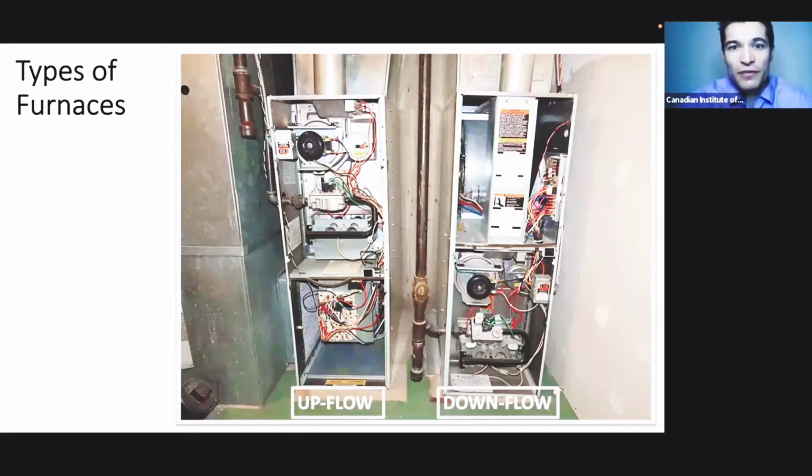After you check the furnace filter, you might want to take a look inside the actual plenum as well, because you see the image on the left, you have the filter rack, you can pull it out and actually look inside the plenum. After you take a quick look down there, take a look inside the furnace cabinet. You can start with the lower one or the upper, it really doesn't matter. But again, you want to be checking for any sort of debris, any sort of corrosion. If there's a motherboard with more modern furnaces, you want to be checking for any loose connections or any scorching, because that may impede the way the furnace functions.